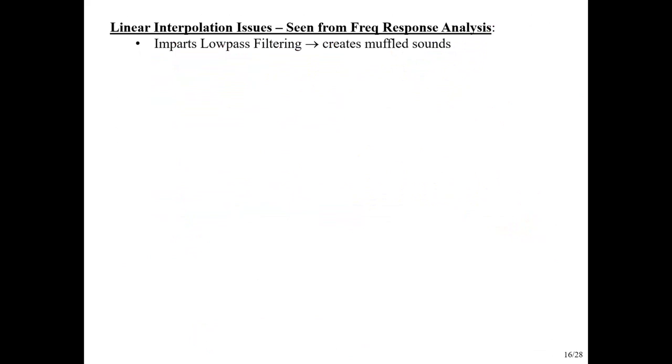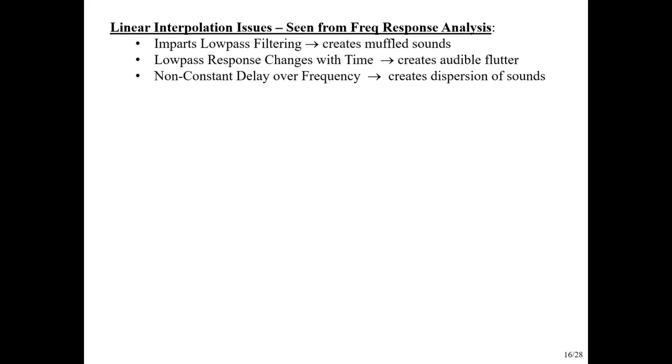So just summarizing some of the problems here. We've got this low pass filtering. Might not be a problem, but probably will be. Muffles the sounds, creates an audible flutter. This non-constant delay over the higher frequencies is going to disperse the sounds.